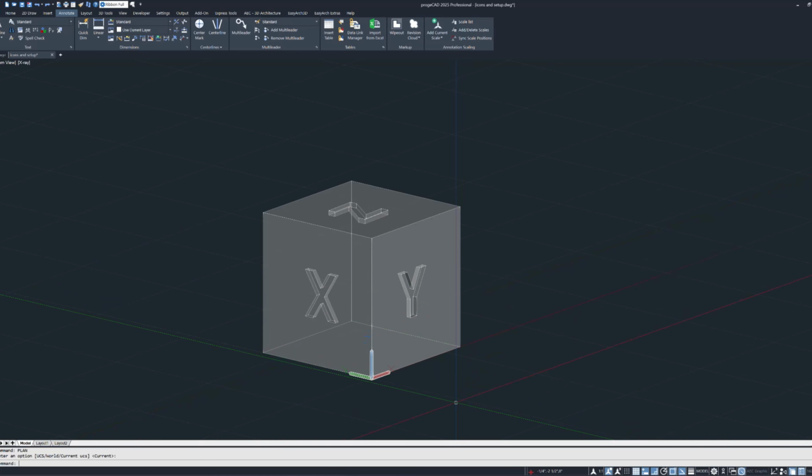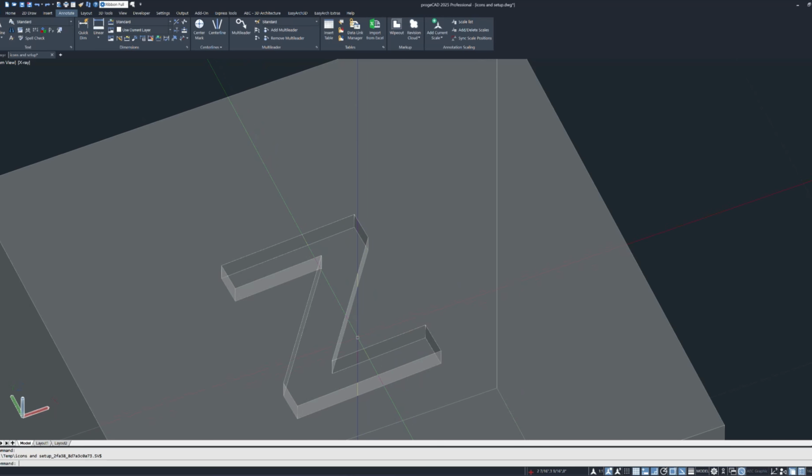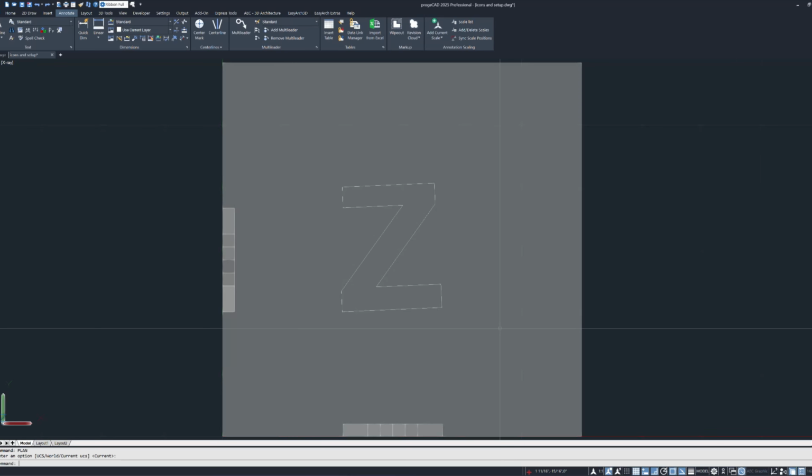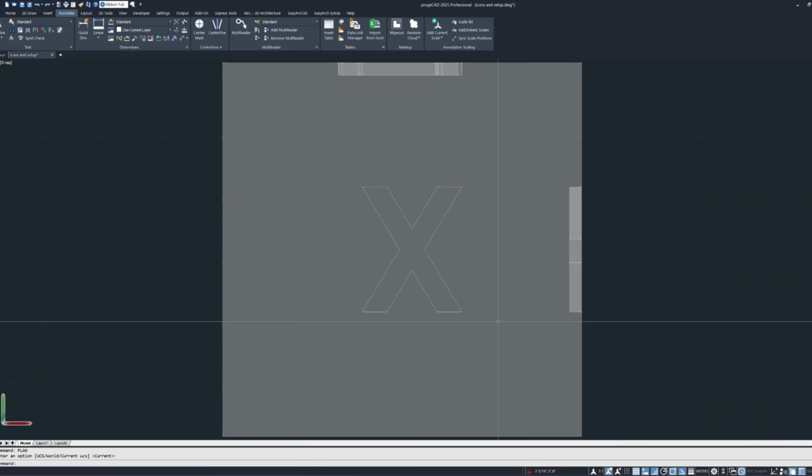Continue these 2 steps of defining coordinates and name saving for at least 3 faces. When switching to a plan view, the first point picked in the UCS command will be at the bottom of the plan we will be drafting at, so that positive numbers can be used in our next demonstrations. Now practice recalling each of these views and make sure they align with what you expected to see. Then we can move on to the next demonstrations of creating useful objects for a 3D print.